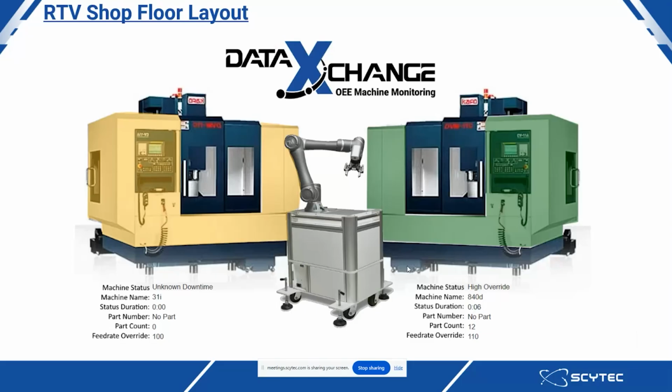Next up, we have another RTV shop floor layout showing 3D equipment, showing the same metrics as in the previous slide. But in this one, we have a Siemens 840D as well as a Fanuc 31i machine, showing us the current status of the machine. So that Fanuc has been in an unknown downtime. The Siemens 840D is in a high override, how long those machine statuses have transpired, the specific part numbers they're working on, the amount of part counts that they've been working on, as well as the feed rate overrides.